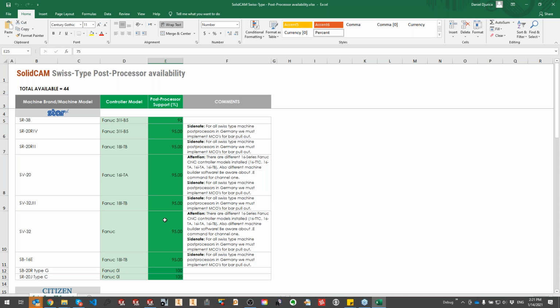You just need to understand that each machine can be different at each customer. For example, with a bar feeder, each customer will have a different bar feeder program, and modifications of such a program have to be adjusted inside the post processor. So for each post, expect that you will need to modify something to adjust for the customer's needs.